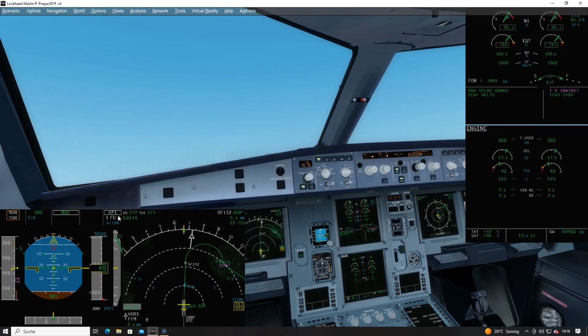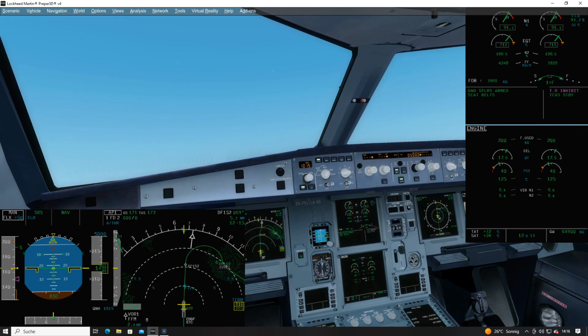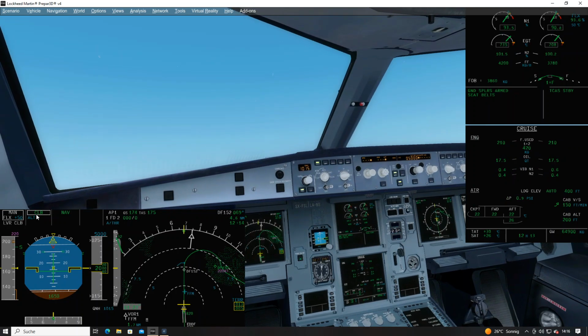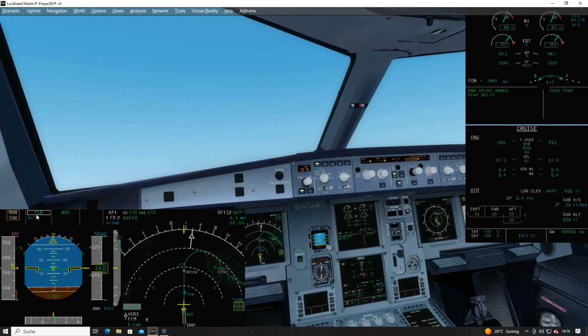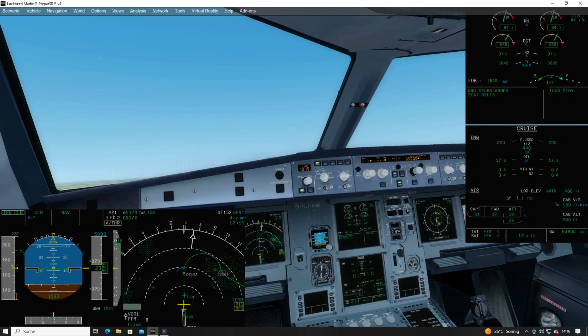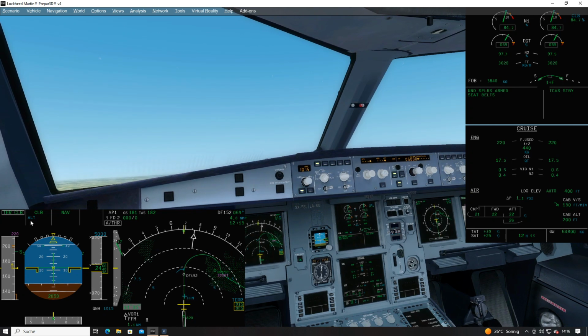Autopilot on is active now here. And then flex 50. We're in the acceleration phase. There's an acceleration altitude coded already in the FMS. Once we pass the altitude, it is now switching to climb mode, asking me to adjust the thrust to climb thrust. Now, there we go. Thrust climb. Climb, Alt blue. The next vertical mode is armed.